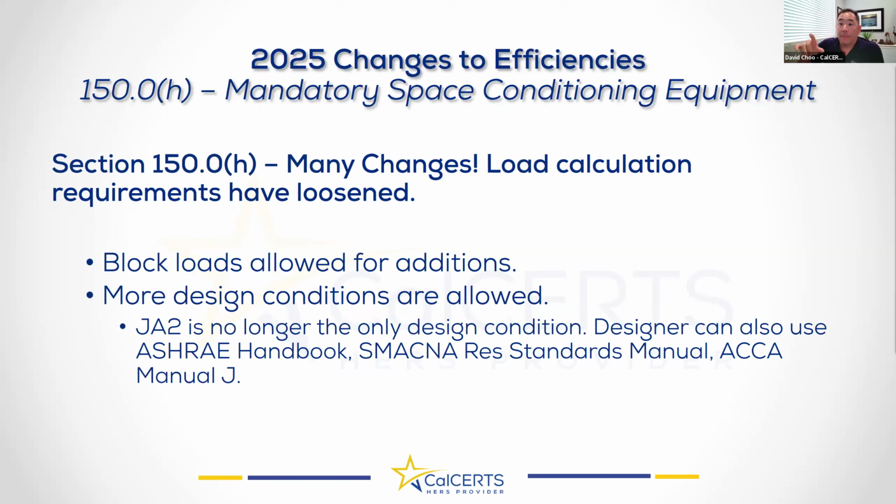Okay, so if you look up top, section 150.0H, or the mandatory space conditioning equipment requirements. What the CEC is proposing is that load calculation requirements get loosened a little bit. For example, for additions, they're now going to allow block loads.